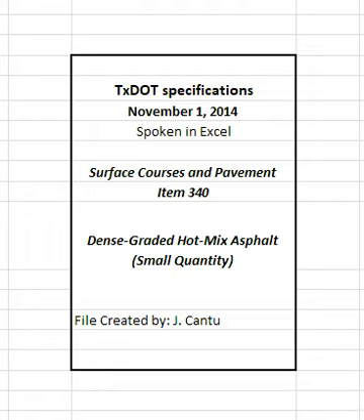Table 3. Gradation requirements for mineral filler. Sieve size and percent passing by weight or volume. Sieve size number 8 with 100% passing. Sieve size number 200 with 55 to 100% passing.